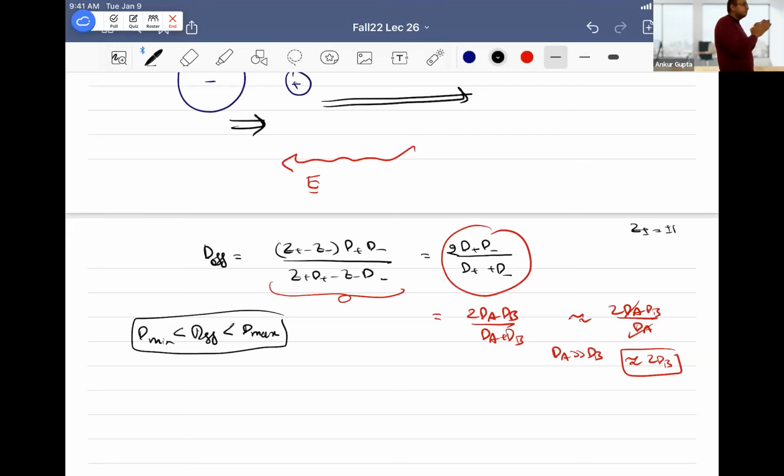So charge density is 0. We simplified the equation and it becomes basically a diffusion equation. But the diffusivity constant is a combination of both the ions. And then if the diffusivity is a combination of both the ions, we derived that to be ambipolar diffusivity, which is always between the minimum and the maximum. Okay, so this is what we have discussed today.